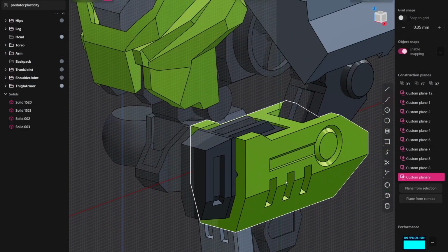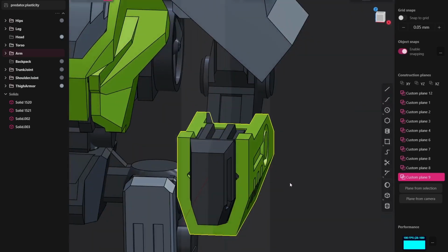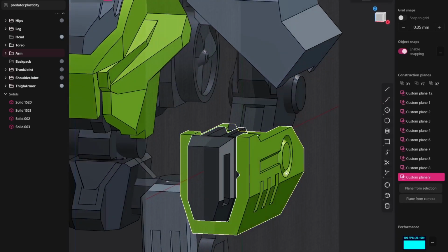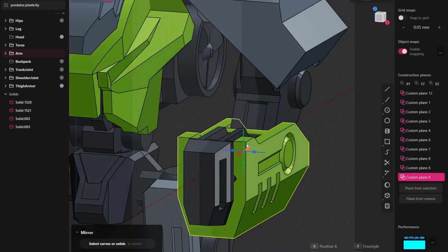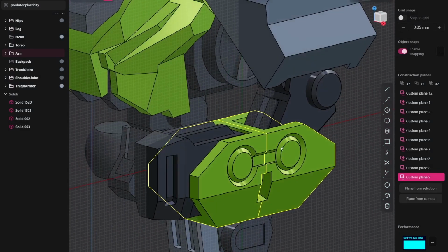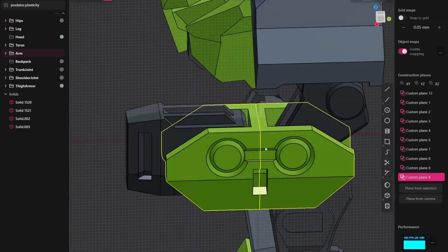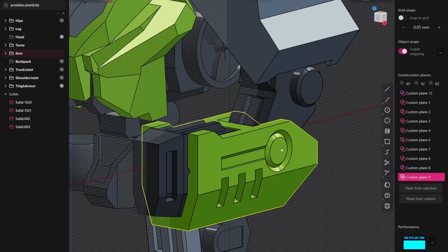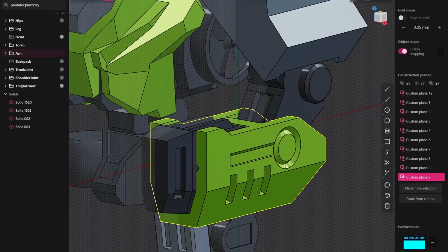And that's it. Now, sometimes it might happen that if you're mirroring something, you will do it on the wrong axis. If I hit Alt X and then I accidentally hit one of the other axes without noticing, maybe you're used to using Alt X and then X again, this will happen. Now, be very careful because you cannot undo this, or rather you cannot take it back to how it was. So you have to Control Z so that it goes back to the previous state. Be extremely careful. Now, obviously in this case, it's obvious, but sometimes it might not.